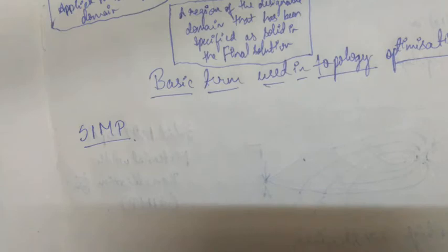As in the video, we have mentioned the SIMP technique very much. So let's see what it is. The basic of the SIMP technique is to determine the optimum structural shape by varying the density of material within the designable domain. The designable domain is generally discretized, while the FE analysis technique is employed to determine the behavior of the structure to be analyzed.